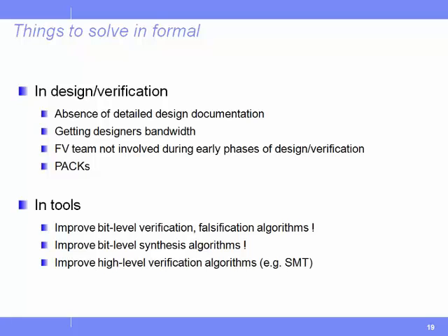And it's also our objective to arrive at more formal verification packages or solutions. For example, a package for clock gating verification or sequential redundancy identification in designs, and for LRU verification we also have some kind of IP where we have the checks as well as the test bench. So that is the kind of packs that we aim to have in order to enable better adoption of FV.